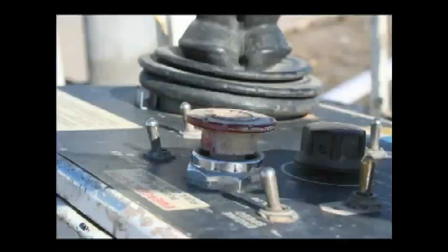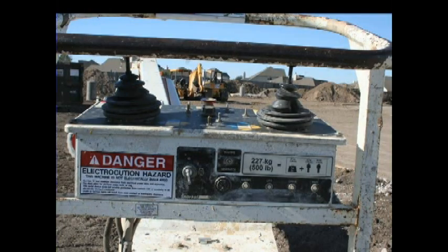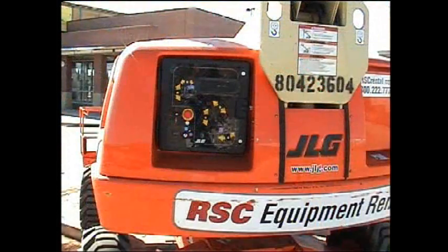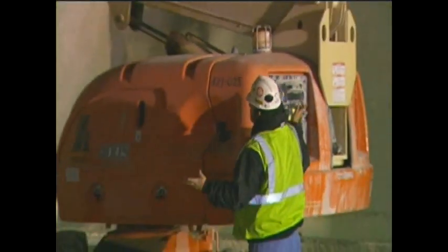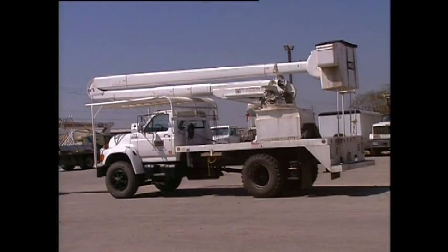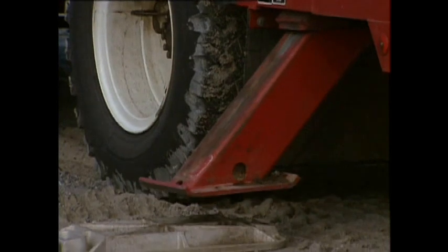Aerial work platforms must have both platform and lower controls. Platform controls must be in or beside the platform within easy reach of the operator. Lower controls should be able to override the platform controls, but should not be used unless permission has been obtained from the personnel in the lift or in case of emergency. Before moving, the boom must be properly cradled and outriggers must be stowed in position.